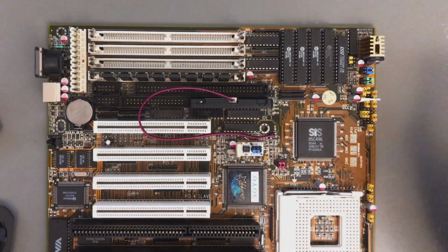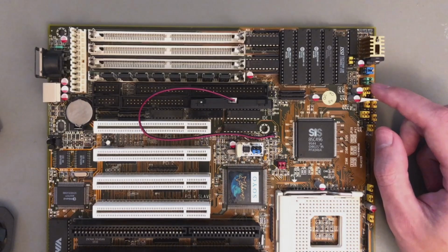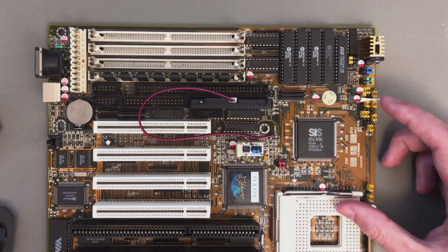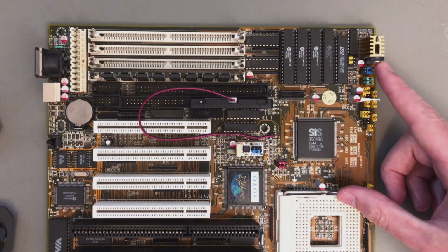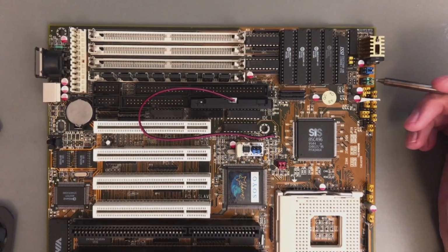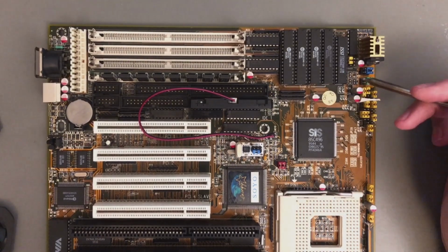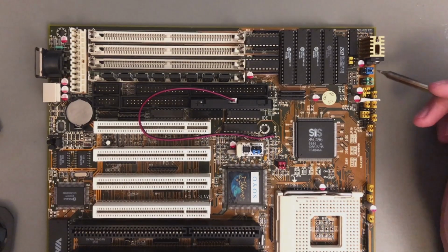So with the Pentium Overdrive, even if you go here and you change the setting from 5V to 3.3, the CPU shorts everything together, so in the end you get again 5V. Not only that, but this is a little bit dangerous because the CPU is only powered by one pin. So in the end, what I did here, and the answer is simple, I just used an external cable to drive directly the output of the voltage regulator to the CPU. And the nice thing is that these two unused pins here are exactly what we need. So just a wire that connects to these two will do the job.